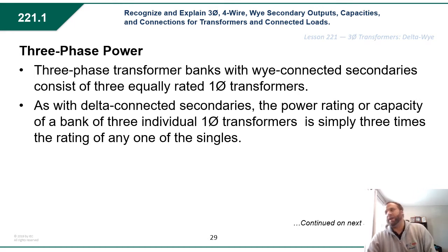In your worksheet or handout that I've given you, there are formulas for sizing lighting transformers. You will need to be familiar with those formulas and how to use them. So go back, look at your notes, identify how to size a lighting transformer. That was found in lesson 220. When it comes to our Y transformers in lesson 221, they are not allowed to be sized differently. You're going to have all equally rated.